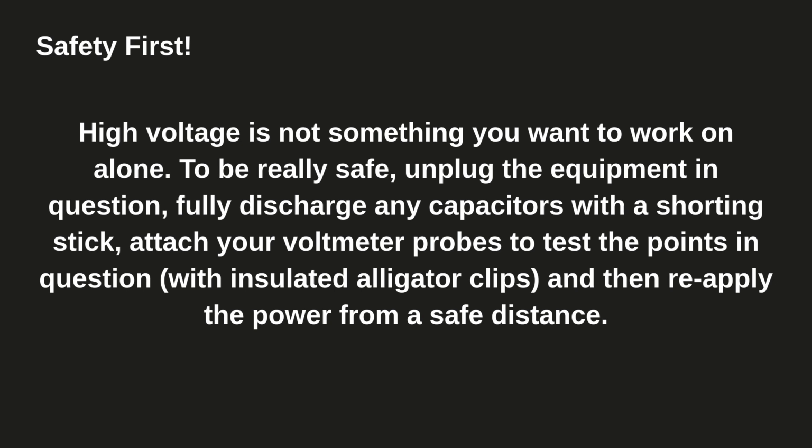Now, high voltage is not something you want to work on alone. To be really safe, unplug the equipment in question. Fully discharge any capacitors with a shorting stick. Attach your voltmeter probes to test the points in question with insulated alligator clips, and then reapply the power from a safe distance.